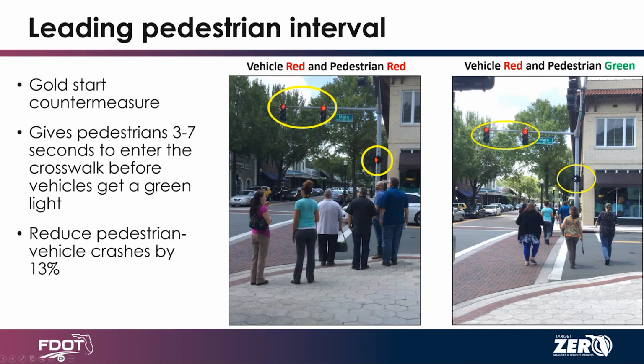There's also some challenges. So the TEM has some guidance with signal phasing. If you're running a protected permissive left turn, most likely you're going to want to lag it, or even a protected left turn, just to avoid late turning conflicts while pedestrians get a head start. There's also guidance now that, whenever LPI is installed, there is a need for accessible pedestrian signals.